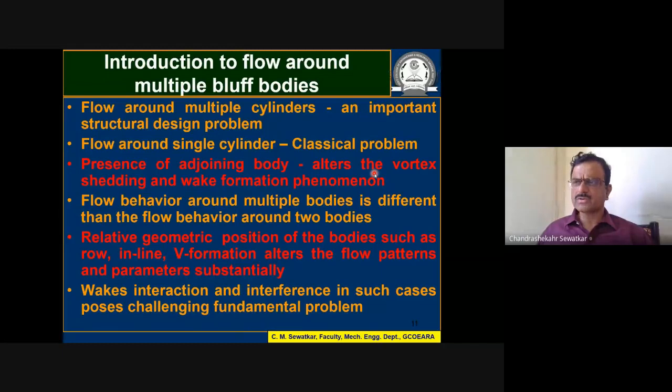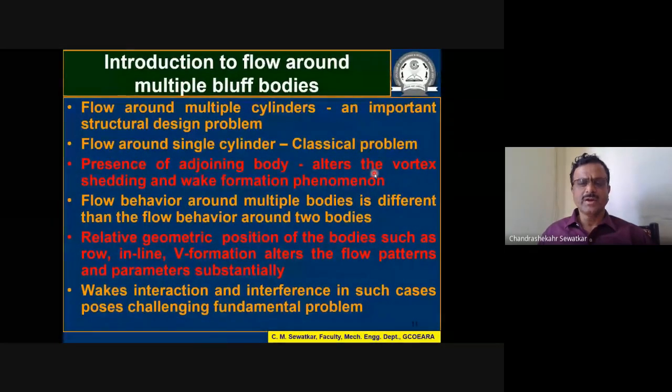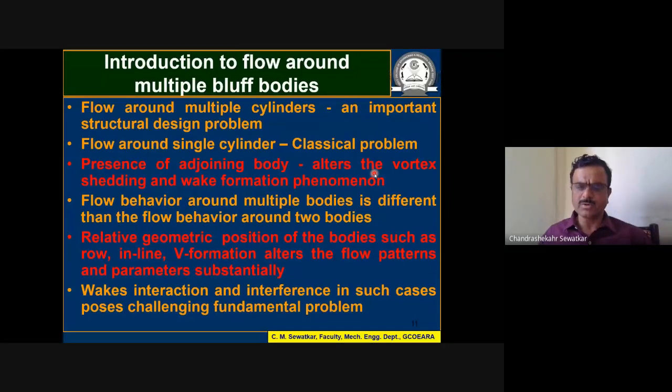But when there are a large number of bodies, the space for fluid to flow around is very less, and that actually creates a lot of disturbances in the wake pattern or the vortex shedding pattern, and it alters the nature of the forces experienced by the body. And those forces, especially when the problem is a structural design problem, are important to us, and hence we will be looking mostly at the forces.